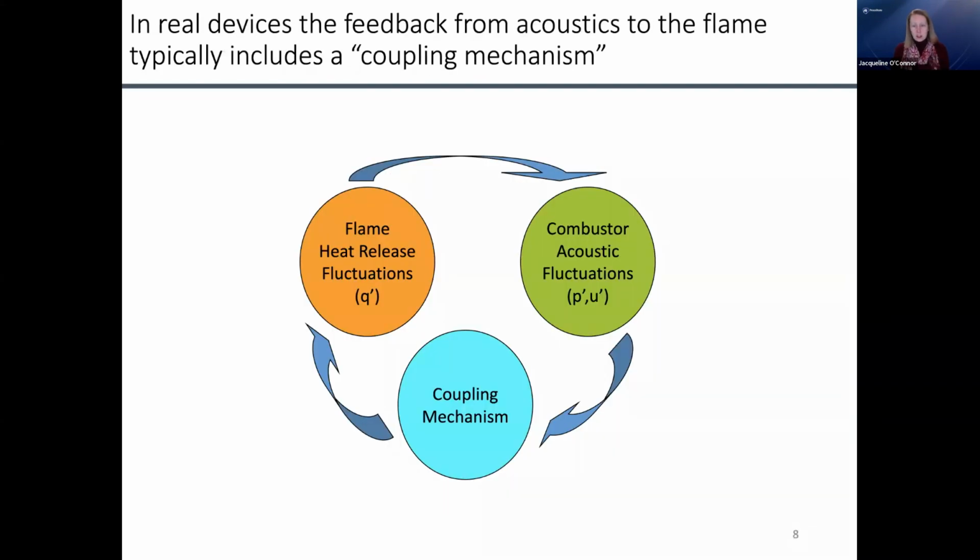So for that particular combustor, when it's unstable, it's about 115 decibels in the room. That tone is about 520 hertz. If you're a musician, at least in the United States, your orchestra tunes to an A440. And so it's really quite a nice tone, but it's extraordinarily loud. And this is just an atmospheric research combustor. You can imagine in an actual engine that these pressure oscillations can be a lot louder.